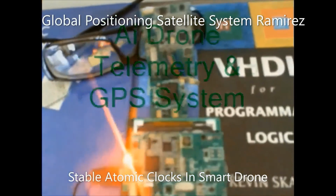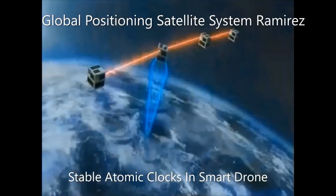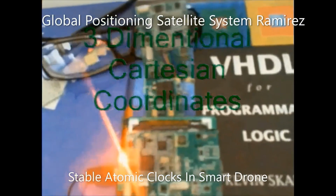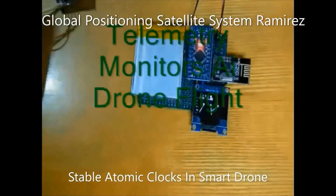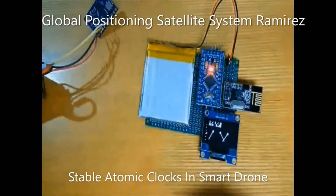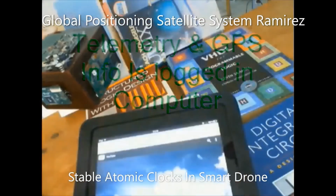Therefore, four satellites are in view for triangulation of the receiver for the drone to compute four unknown quantities, that is, 3 position coordinates and clock deviation from satellite time.